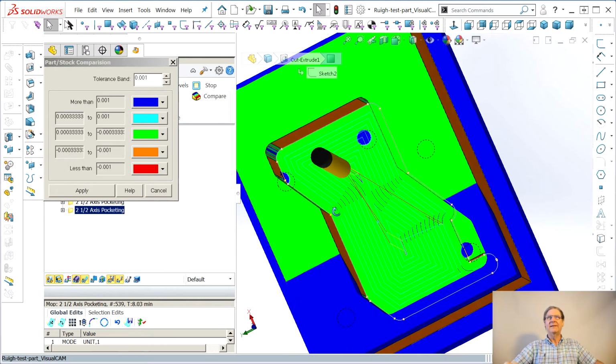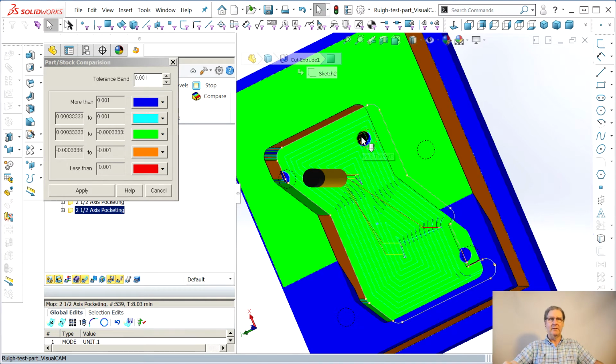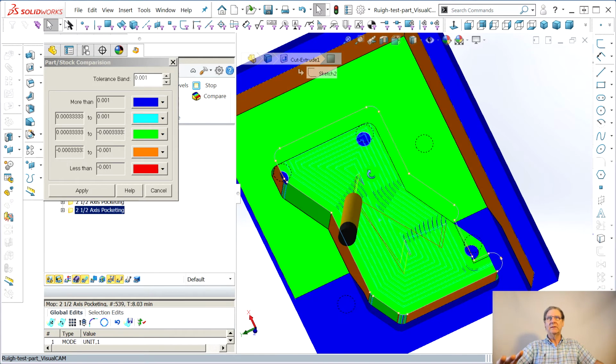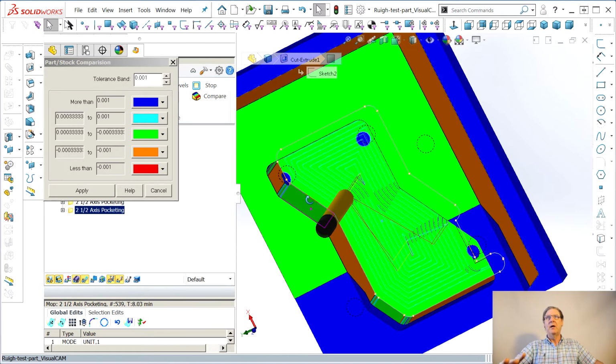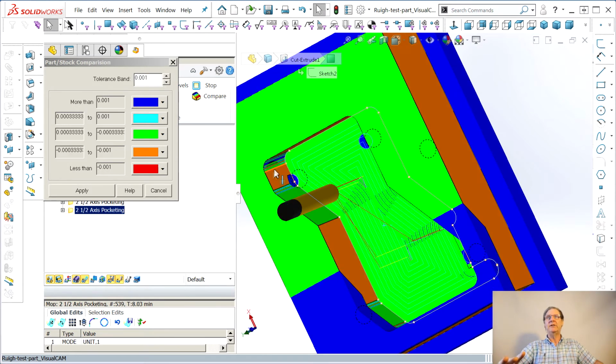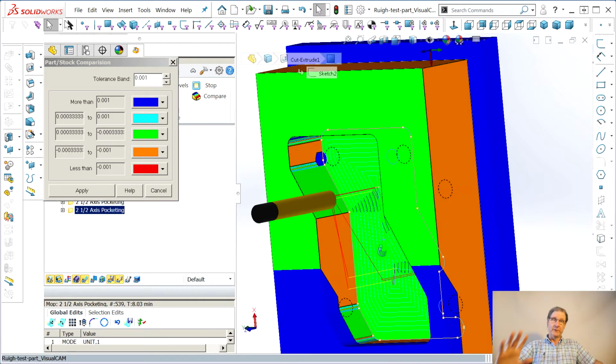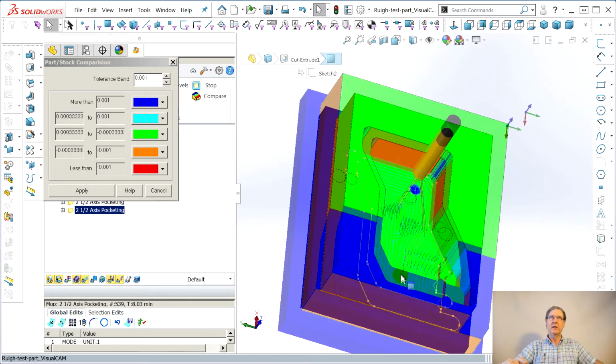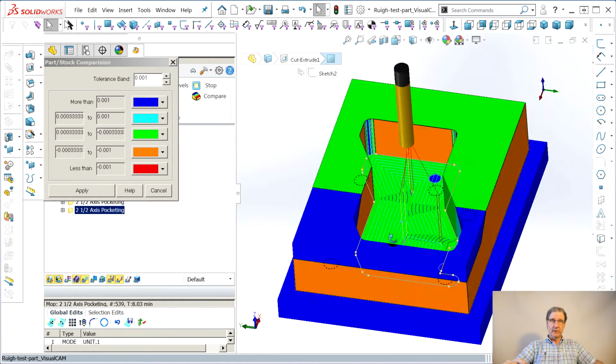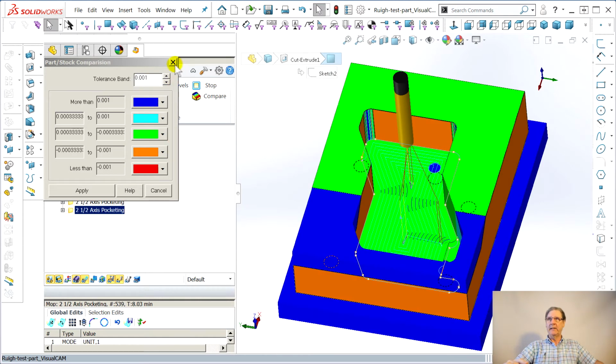And then, the hole here, that's going to be drilled up from the bottom. Same with this one we bridged over. But it didn't change anything like the SolidWorks CAM when before I made the sketch and did all that. It actually did a little gouge up here because I got confused with its automatic feature recognition, which I had more trouble with than it's worth. So I say OK.